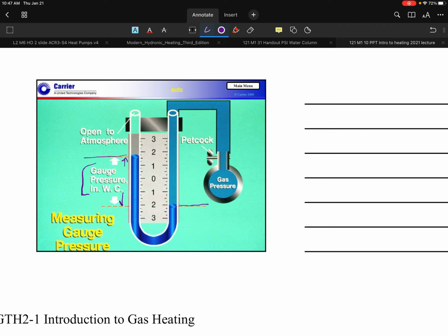Based on what I can see, in real life, if this were zeroed out and this manometer were to push it down 2 inches this way, then it would have no choice but to push it up 2 inches. Now you'll notice, when you look close enough at the scale here, it's probably closer to 1.5 here, and probably 2.25 or so here, which tells me that whenever this started, it wasn't really zeroed out.